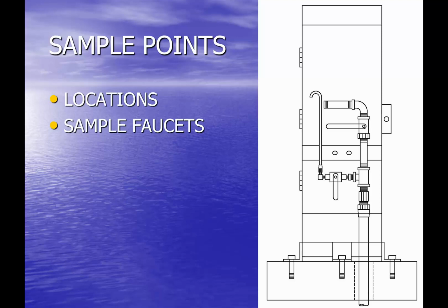You minimize the potential for false positives on anything when we're controlling the sample point, as opposed to a sample point within a customer's home, where I don't know what's happening between the time we were there and the time we were last there. So the book implies that sample points are primarily located in residences or businesses, but in reality, most public systems today are going to have these dedicated sample points.